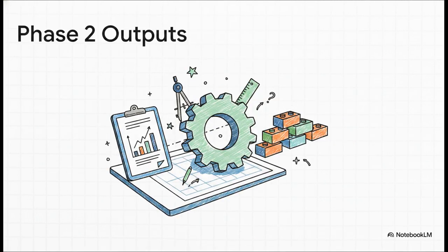Moving right into Phase 2, product design, those early goals take a near final shape. This phase yields vital outputs like the finalized bill of materials, tool and equipment requirements, and the design failure mode and effects analysis, or DFMEA. The DFMEA helps identify exactly how a design might fail so you can fix it before it actually happens.